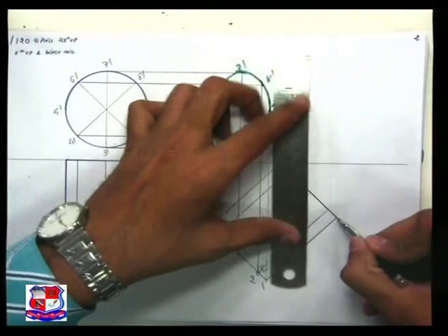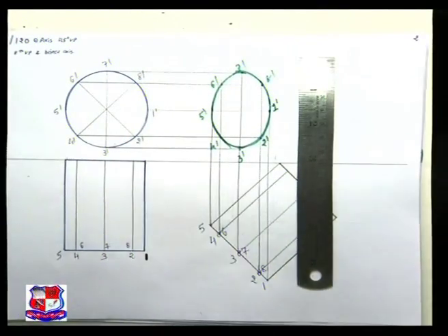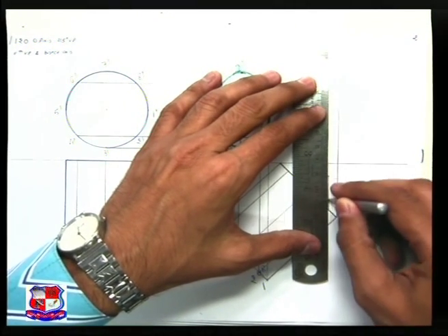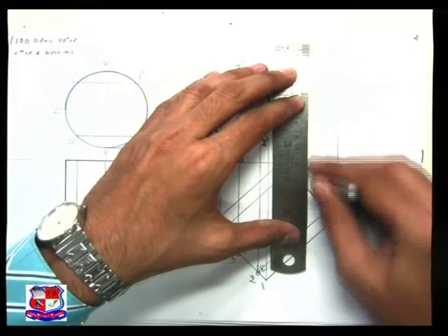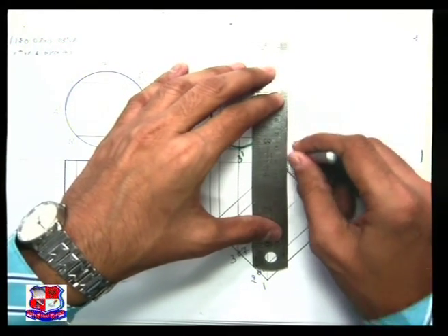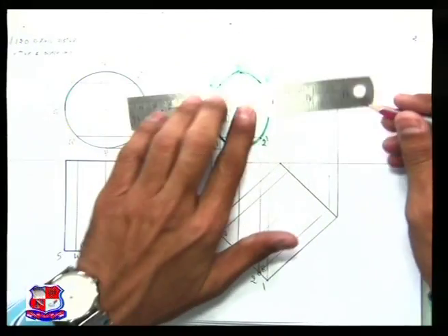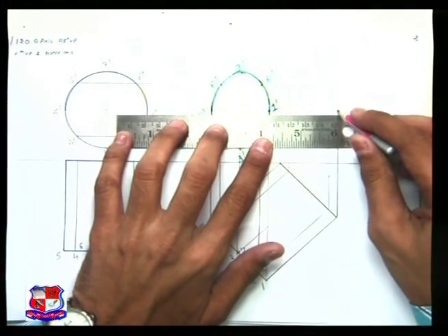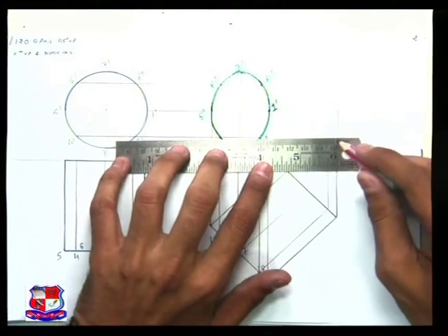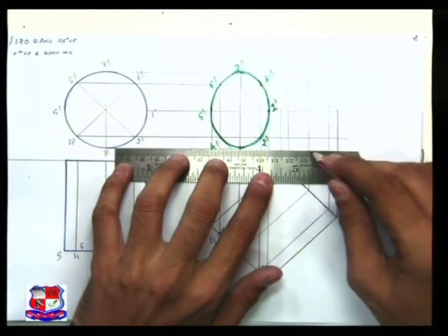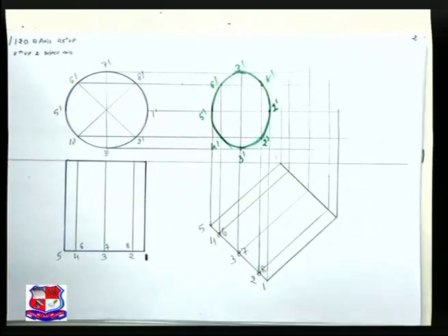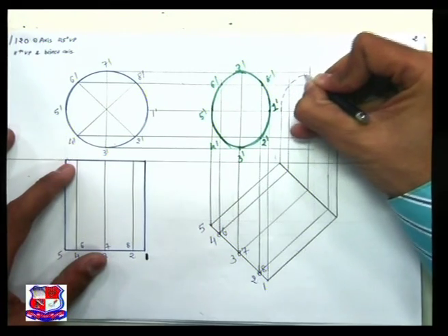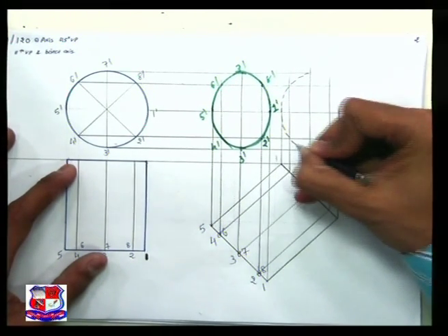Now what about this bottom face? For this bottom face also repeat the same steps. Vertical lines from all these endpoints like this, all these 1, 2, 3, 4, 5, 6, 7 and 8, or you can give any name, and horizontal lines from all these points. So here also we do have 8 more points over here, and all these points should be joined with the dotted line, as they represent the hidden portion, like this. Join with the dotted line.